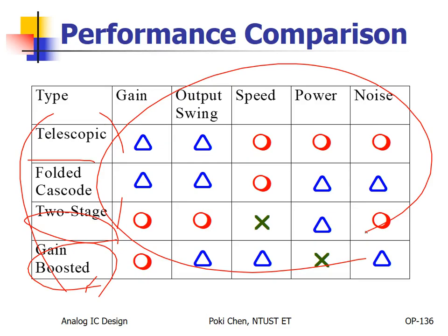From the beginning, you need to select one structure to fit your application instead of creating a new one. No, forget about it. Even though I taught you already how to create a new one in a systematic way, my recommendation is never use it. Never apply such kind of systematic way to invent a new one, with about 100% certainty your new op-amp won't be functional.